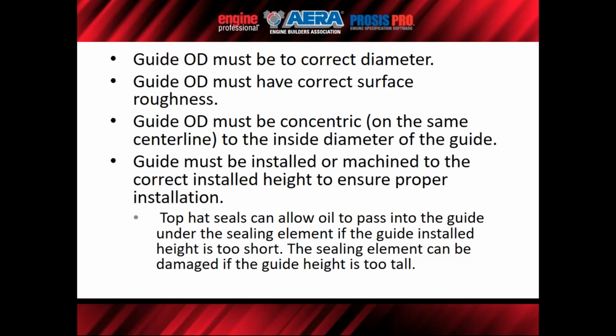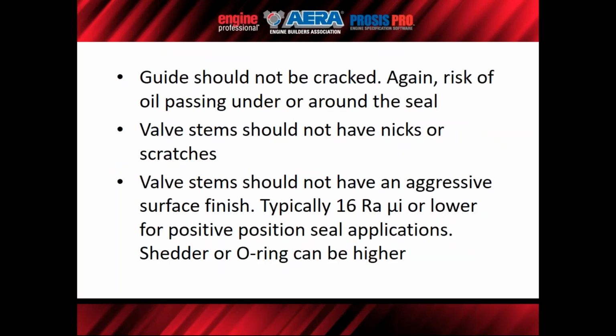You can have situations where oil can migrate under the guide and then still be sucked down into the combustion area. And again, as I was speaking to earlier, you can just shear the material by having a guide that is too tall. The guides should not be cracked. Again, risk of oil passing around or under the valve stem seal.